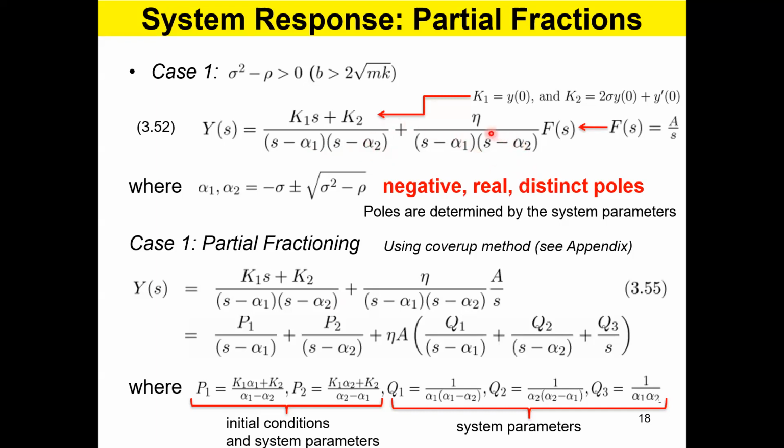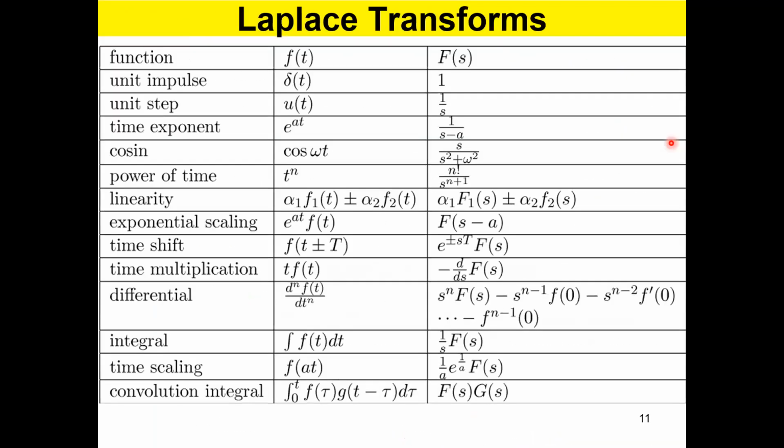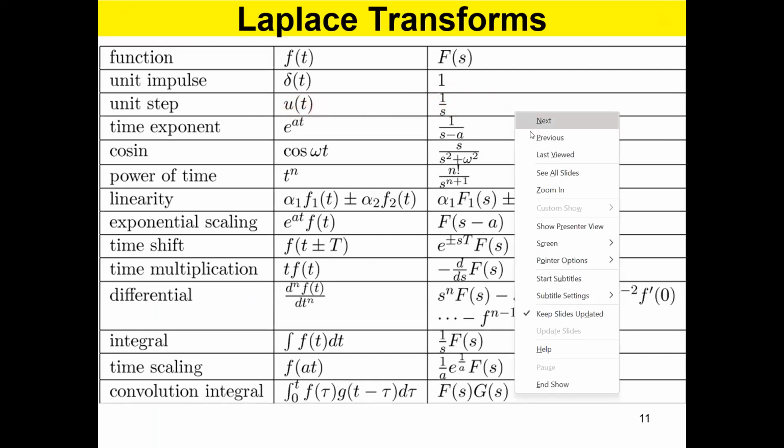And the other thing I want to mention here is that this Fs is the forcing function, external forcing function. We have to pick up a forcing function for this one. So why don't we try to see the real world? So you have, say, 50 kilograms, you're a 50 kilogram person, and you jump on the seat. So it's like a step input to the plant with 500 Newton force. So you can put it like that, A over S. A is 500. This 1 over S means step response, right? If you go back to Laplace domain, you can see 1 over S is equal to ut. ut is the step signal. You know that, right?